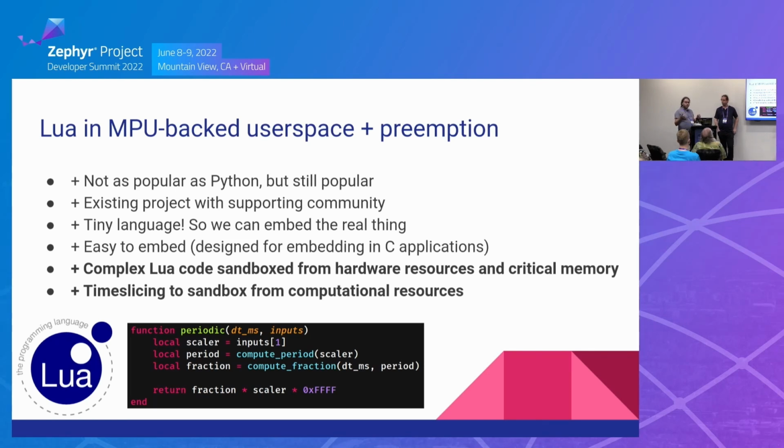And if we turn on time slicing, then we get real-time constraints. They could lock themselves in a loop, but they're only going to be locked in a loop for 10 milliseconds. And as long as we set up our priorities right and we reserve enough time in there for servicing the hardware that we need to service, they can make it so that their code isn't hard real-time, but they can't prevent our code from servicing whatever it needs for safety or duty cycle management or power management.